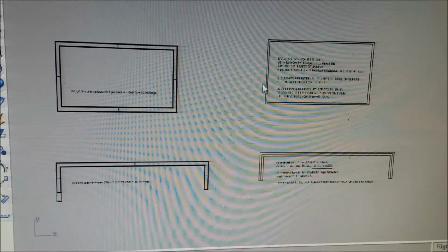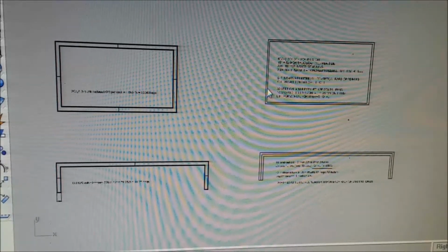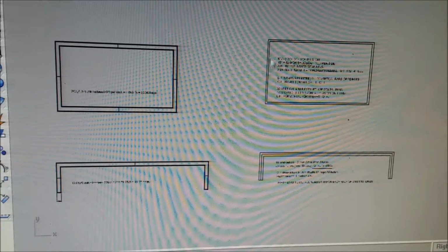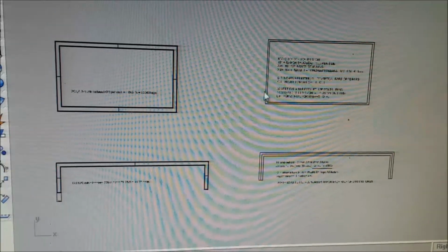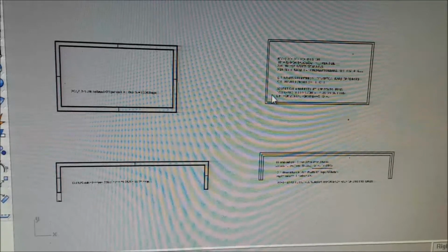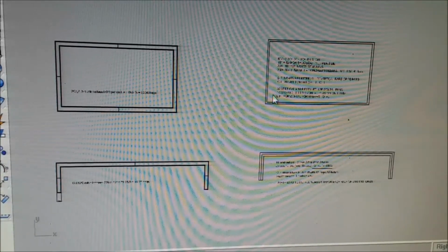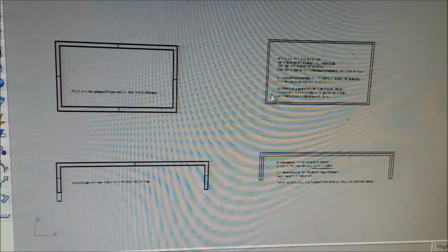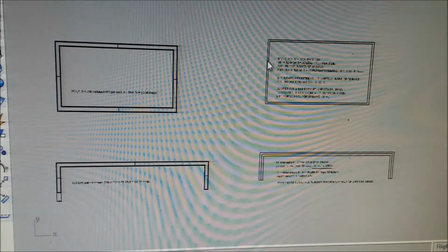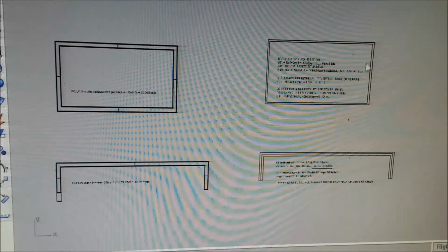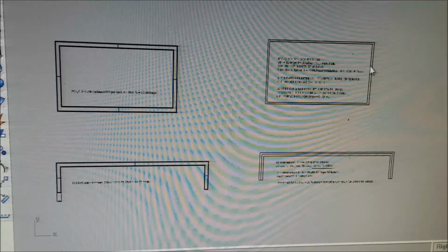And the rebars, that's sort of a puzzle. You have to figure out what length of the wall it is, and how many vertical bars you need. That's the space bar to bar, divided into the length, tells you how many verticals you've got. The horizontals, you figure out one band around whatever you're doing, and then multiply it.